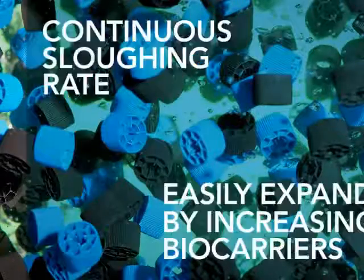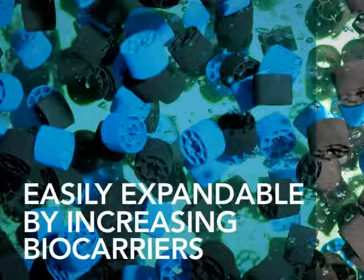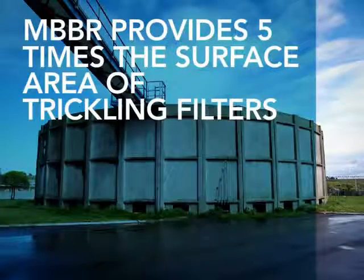Treatment capacity can easily be expanded by increasing the fill fraction of the biocarriers within the reactor, as much as 70% by volume. At equal levels of BOD removal, Headworks BIO's MBBR provides up to 5 times the biofilm surface area of a trickling filter, using less than a quarter of the reactor volume.